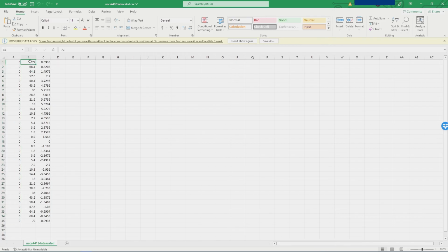And then I took those points that range between 0 and 1, or actually -1 and 1, and I just multiplied them by 72 for 72 inches, which is 6 feet. So like, the chord length of a Cessna 172 is roughly 6 feet. So multiplying it by 72 gets me inches. Oh yeah, and I saved this as a CSV.